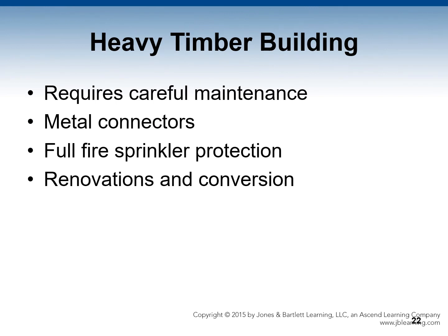Then you have heavy timber building. This requires careful maintenance. Metal connectors may provide a heat path. Only a full sprinkler protection can prevent disaster. Take note of renovations and conversion to new use.